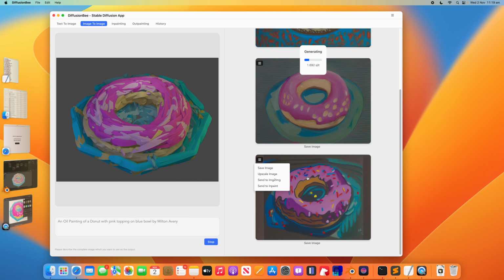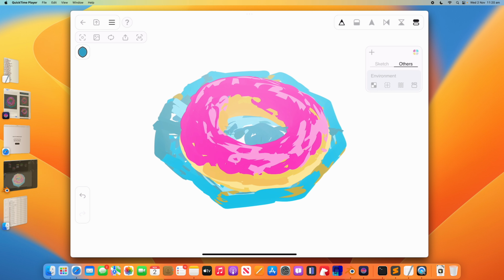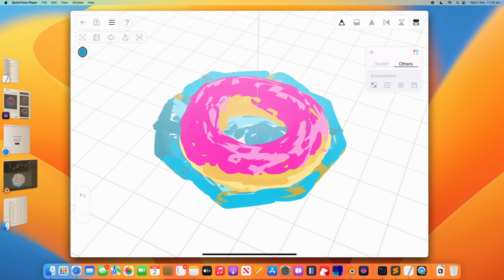Let's delete this. Back to Feather. Where is the option to have the grid? If you want to draw like a wing, for example, you go to the top front view. Let's say, okay, actually go to the side view and then you draw like a line like that. That's gonna be the reference, right? And you go to the front view. We already have reference. We want to have like a wings, so we can